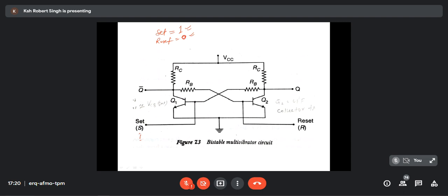So let us think that this is 1. This is 1 means plus 5 volt, or this is high. If this is high, this is P type, this is N type. So this is nothing but an NPN transistor. Why do I say that? Because this indicates the forward bias. Emitter to base should be forward bias. That means this should be P type, this should be N type, and this P is connected to high. That means this is now in forward bias. Okay, very good. Then this will conduct, and this will be on.